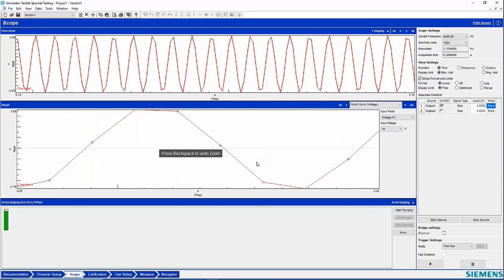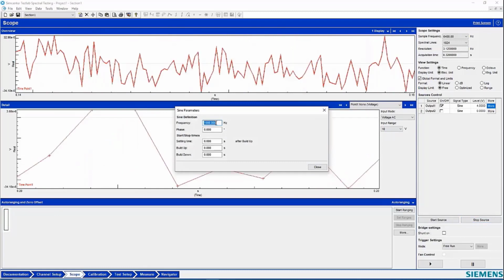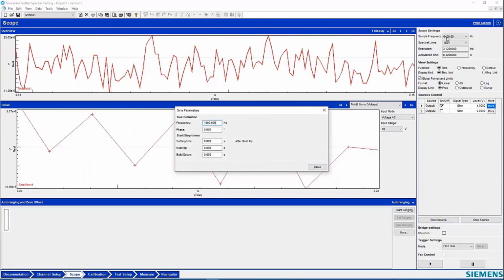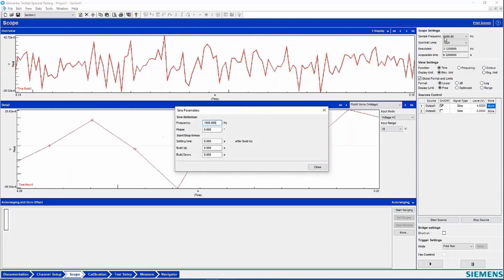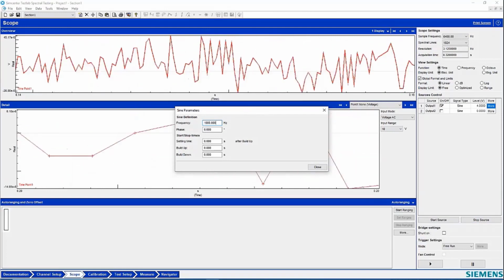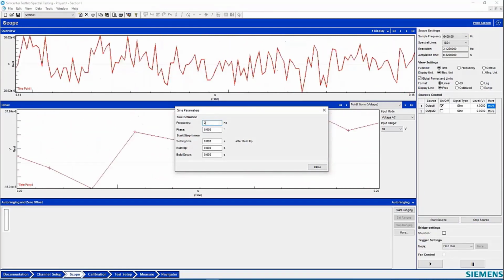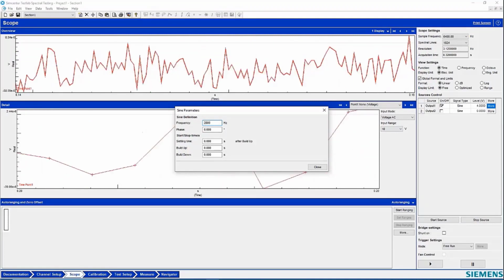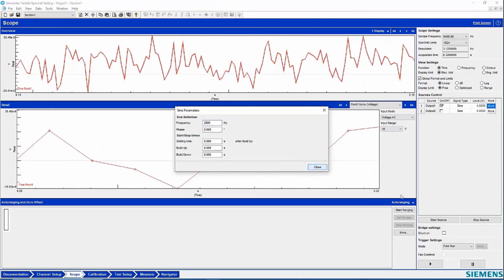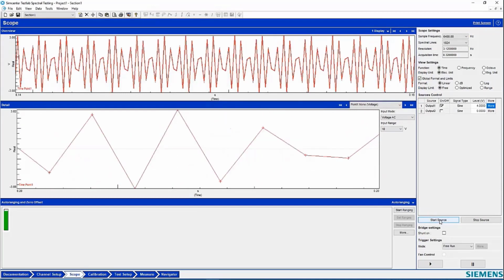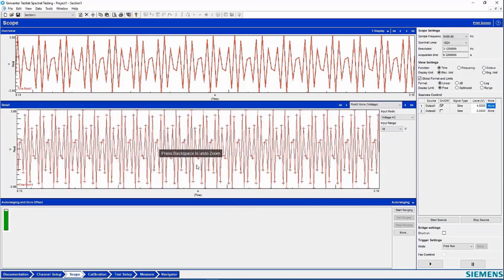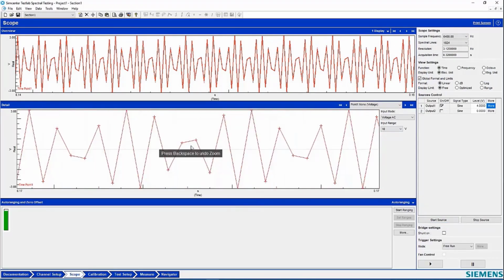Now, I think maybe we can zoom this up a little bit more. You want to pick a frequency, Charles? What would be kind of interesting? The highest frequency I can measure is 3,200. Yeah. So if I went to, I don't know, something like 2,800, let me try that. Let's see how bad it gets. What do you think of the sine wave now? I'm not sure I see a sine wave. Yeah, we're definitely missing some of the amplitude.